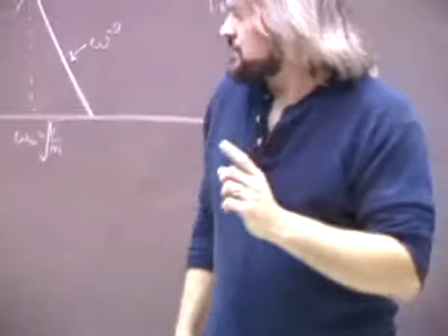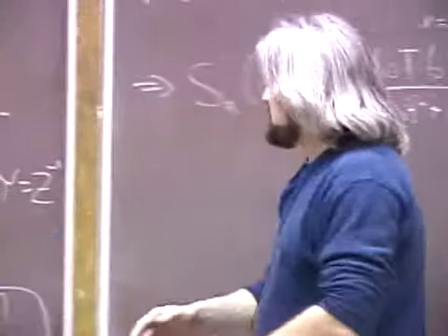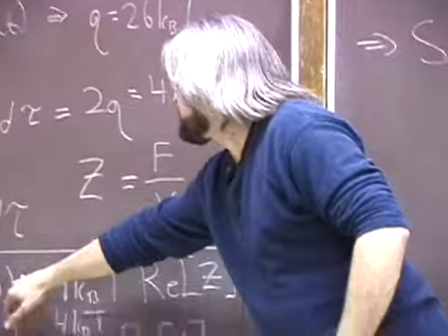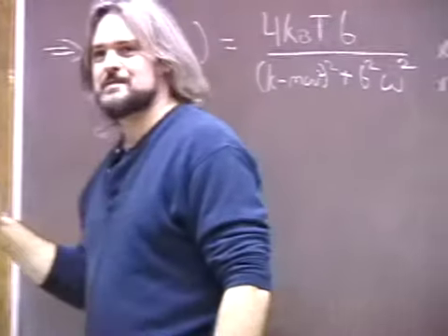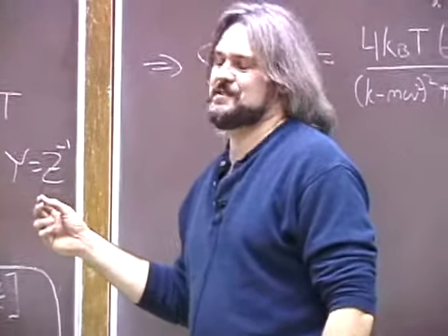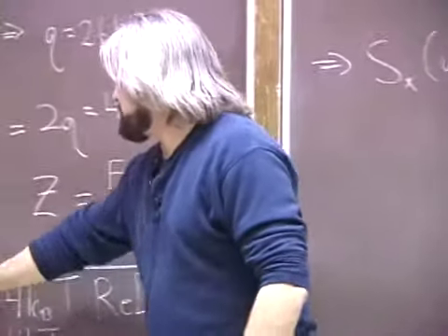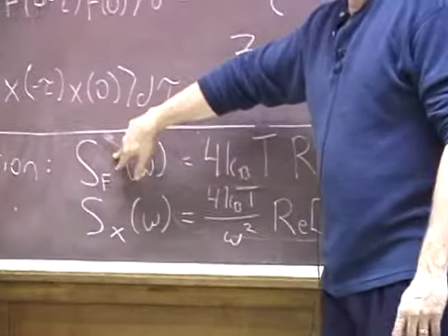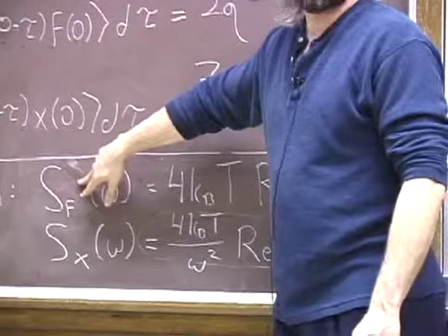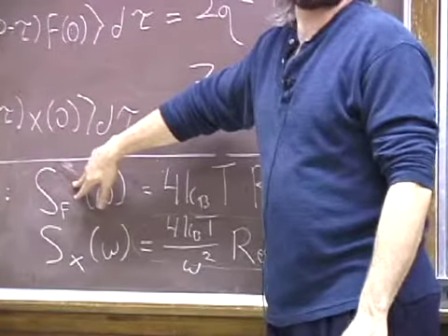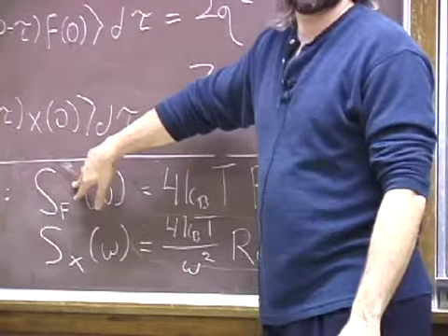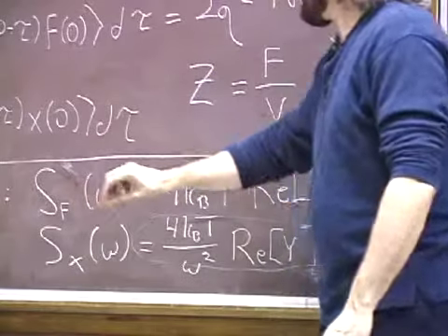What this means, experimentally, is that if you want to study thermal noise, you're given two choices, a fairly easy one and a fairly hard one. You can measure thermal noise directly, and this can be done, but it's very difficult, because measuring a very faint noise in the presence of many, many other noise sources is a very daunting effort.